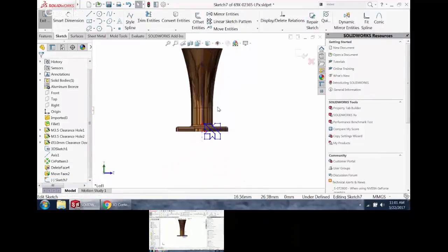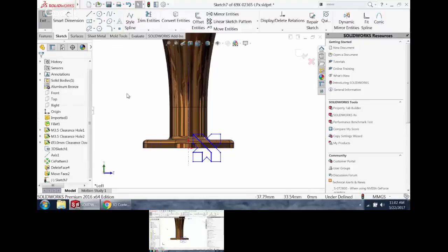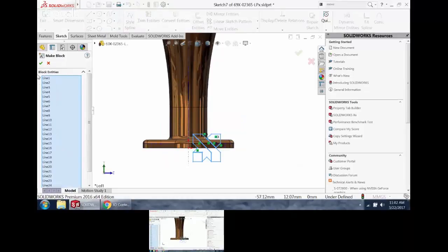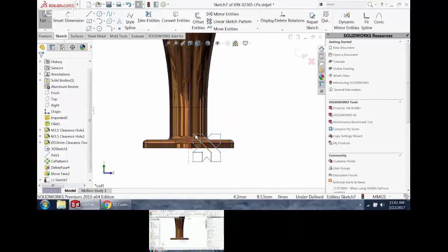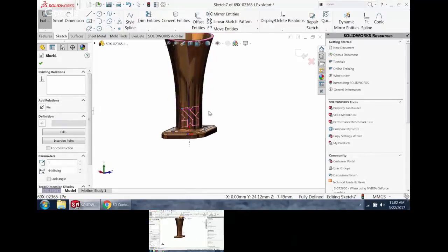So I go into this part and I grab this, that's not the logo anymore. So don't do that. Before you do anything, you want to capture that shape. I'm going to just do a box select to grab everything and turn it into a block. Now, it moves all as a unit. Also, I can change the angle or the scale that it's at. So it does a lot of stuff for me as far as making my life easier.